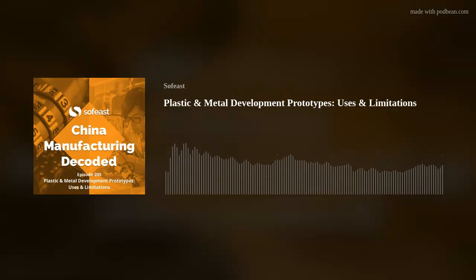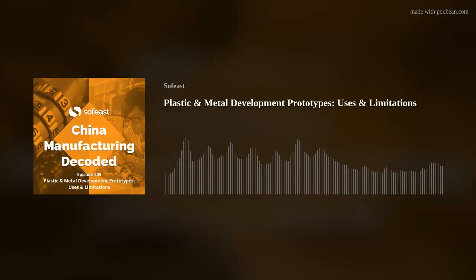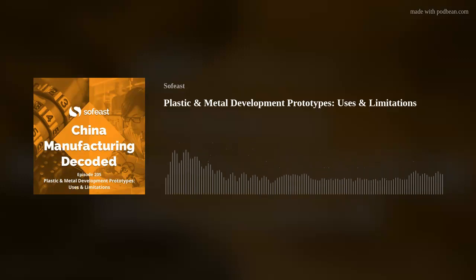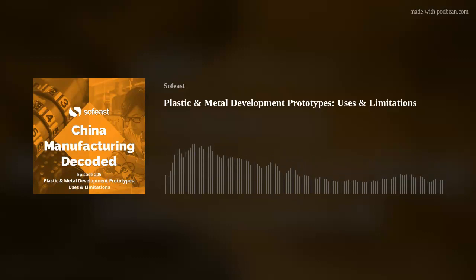And I can hear everyone saying, "Well, just CNC machine them." That's not a problem. Well, yeah, we can CNC machine them. That's not a problem. But again, there are limitations with respect to if it's going to be a high pressure die cast complex housing for a motor, for example. Can you get all of the undercuts? Can you get all of the cavities machined out correctly from a CNC machine? Maybe, maybe not. Again, we need to have a look at the limitations on that.